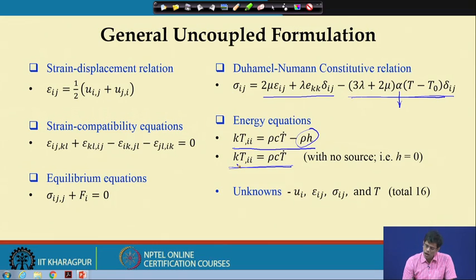So, finally, the unknowns are these unknowns. One of them is temperature, which is additional due to thermoelastic deformation. Now, since we are forming the uncoupled elasticity, uncoupled elasticity means the heat conduction can be solved separately, and the deformation or the Navier's equation of elasticity can be solved separately once we know the temperature change, specifically delta T. So, this delta T is T minus T0.